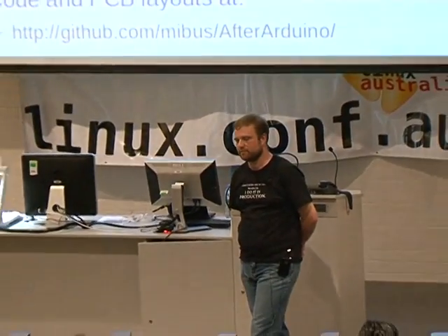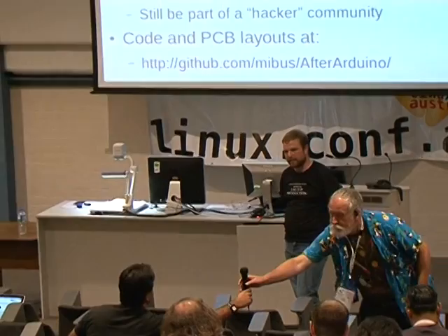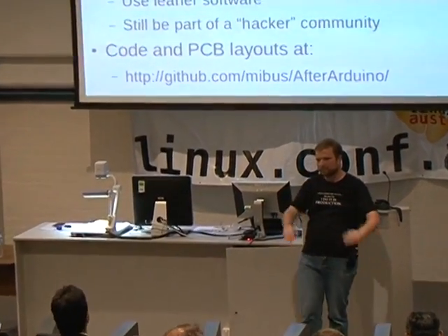And the other thing was the bit shifts. AVR-libc has a _BV macro, which masks away all of that stuff, which makes the code a little bit easier to read, maybe. It does. I did consider putting that in, but I actually prefer the way it reads this way because it hides a bit less of what it's doing, and it's about the same length anyway.